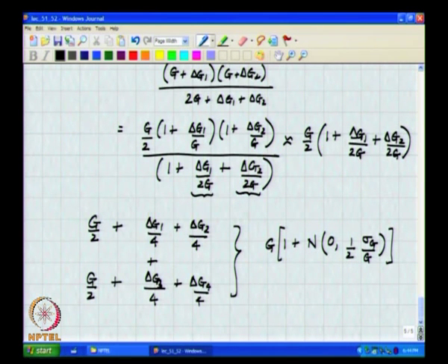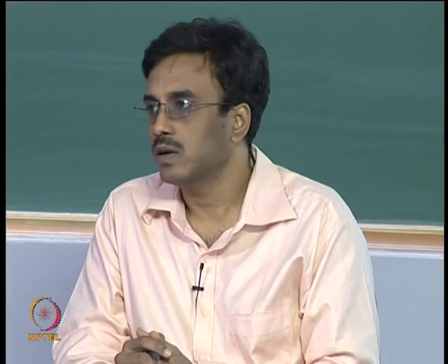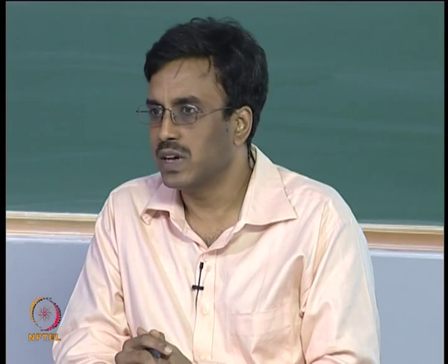alright. So, in other words, if you want increased matching, you must be prepared to have a physically large element, whether it is a transistor or whether it is a capacitor or whether it is a conductance, alright. Improved matching means larger area.